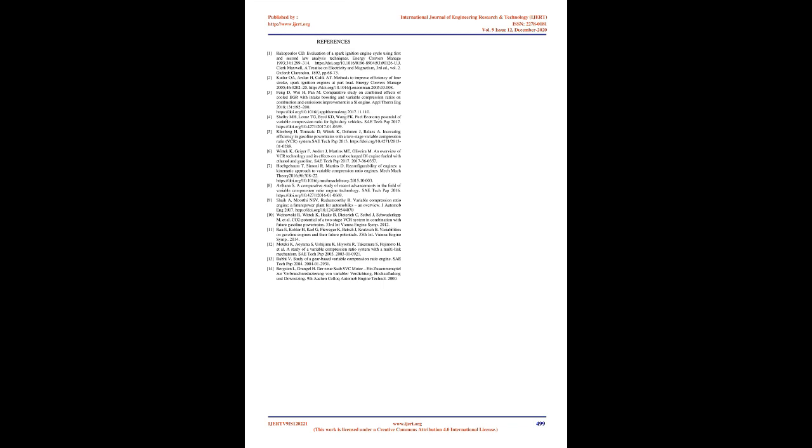So now we have a 2-valve, 3-cam profile arrangement, in which 2 profiles are for getting the conditioned air-fuel mixture inside the combustion chamber and the other valve is for exhaust gases. In such a structure, the valve closing and opening is divided into 2 parts. 1, fully mechanical exhaust valve. 2, electro-mechanical arrangement air intake valve, fully mechanical exhaust valve.